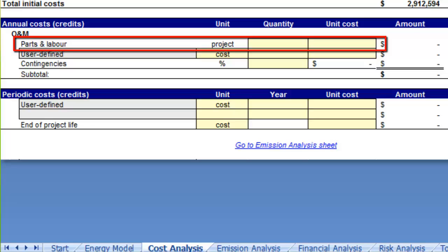When the maintenance of transmission lines associated with a power project is required, it may involve periodic clearing of trees or replacement of parts that become damaged due to lightning, impact, or other causes. The annual cost of transmission line maintenance is often estimated based on the capital cost of the transmission line and substation. For utility-scale projects, annual costs normally range between 3 and 6% of capital costs depending on the location and communication equipment required.